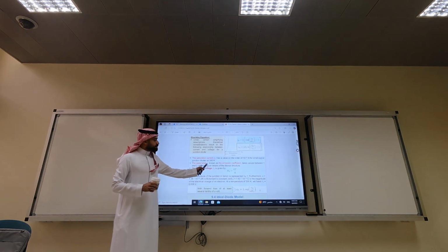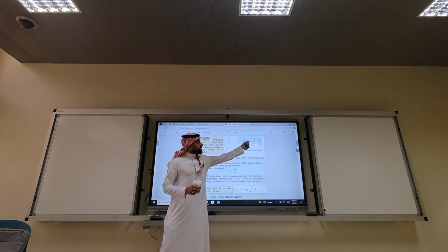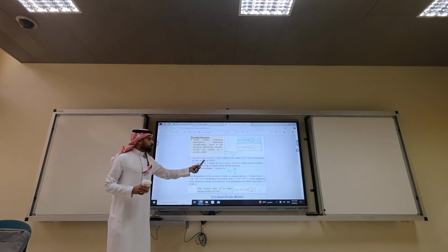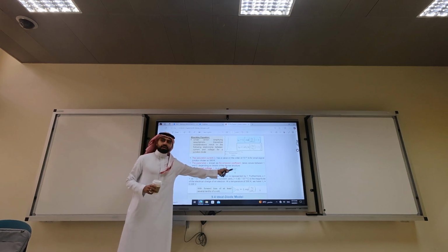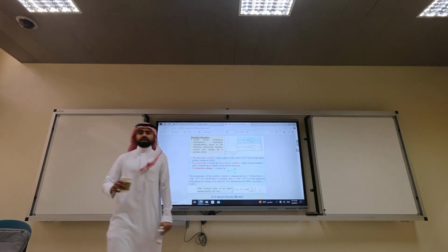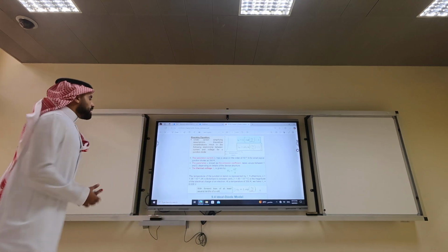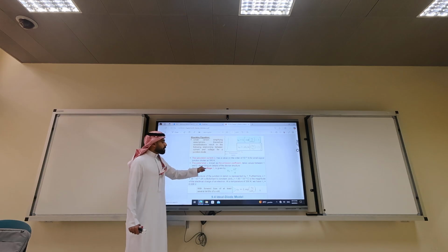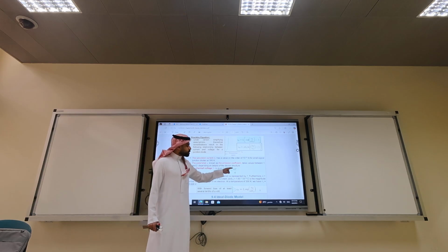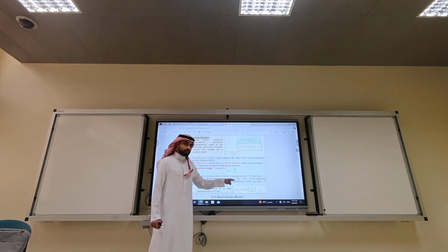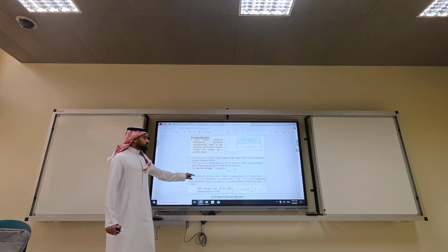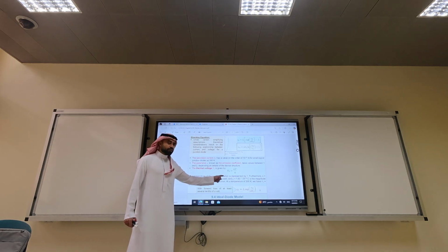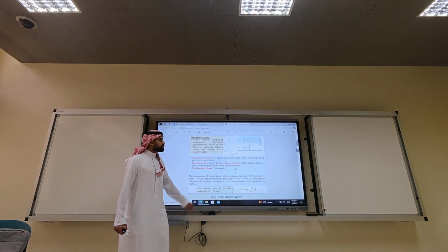The parameter N can be either 1 or 2, okay? Depending on the device structure. It should be given in the equation. The last quantity is the value of VT, which we call the thermal voltage, which is a multiplication of 3 numbers, K times T over Q. So what is T? T is the temperature in Kelvin. Remember, you have to convert from degrees Celsius to Kelvin.